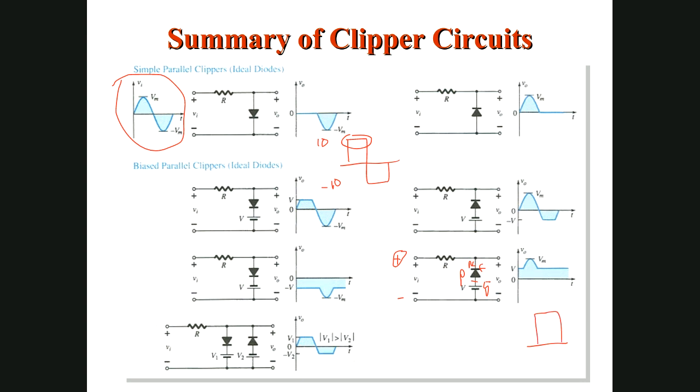Now if you talk about the negative half, your signal will be opposite. In this case, your diode is forward bias, thus it is short. So how much is the voltage? Voltage is between these 2 points, and since this diode and battery are parallel to the output, and the diode is like short, the voltage between these 2 points is 5, so your output is also 5. So you will get your signal like this. It is 10 and it is 5.